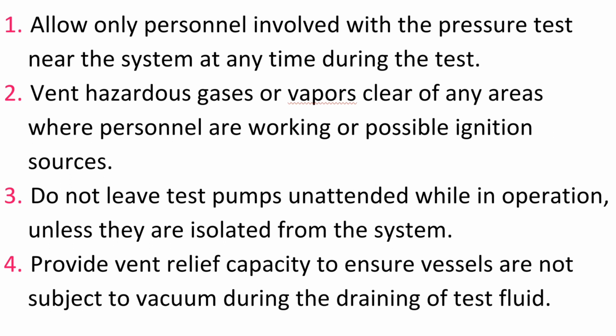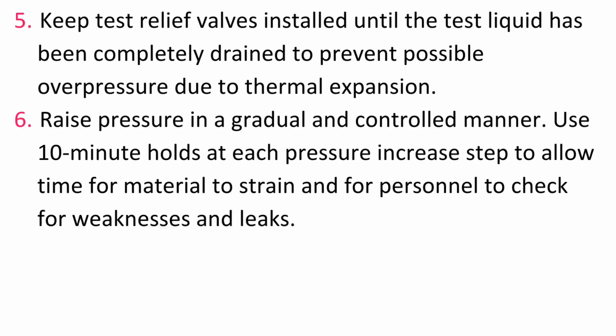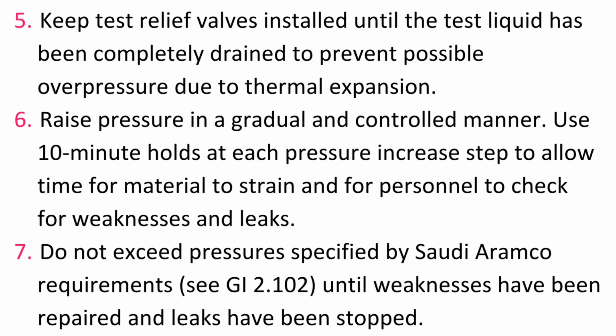4. Provide vent relief capacity to ensure vessels are not subject to vacuum during the draining of test fluid. 5. Keep test relief valves installed until the test liquid has been completely drained to prevent possible overpressure due to thermal expansion.